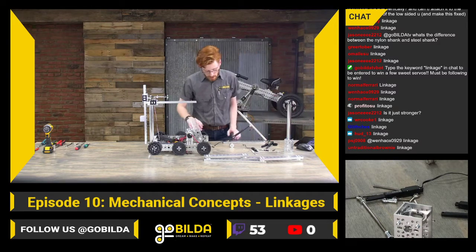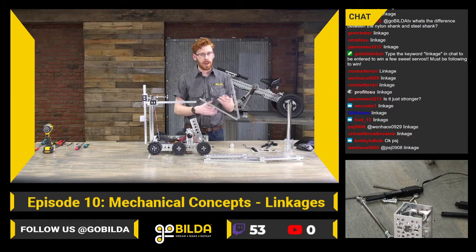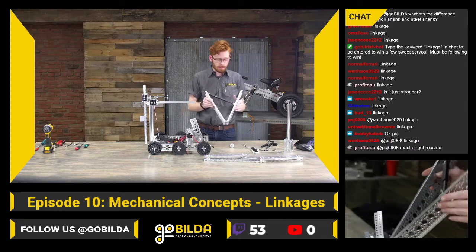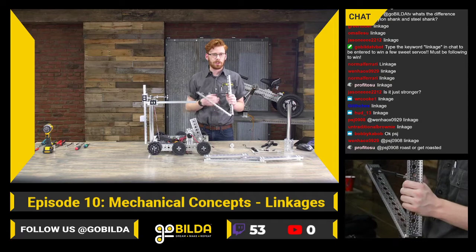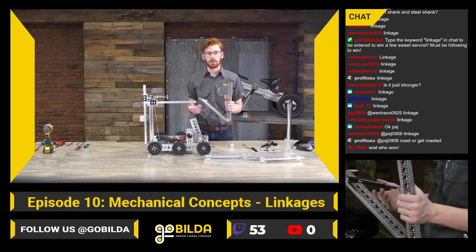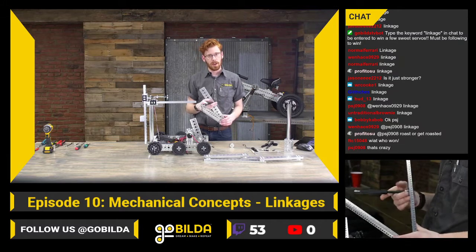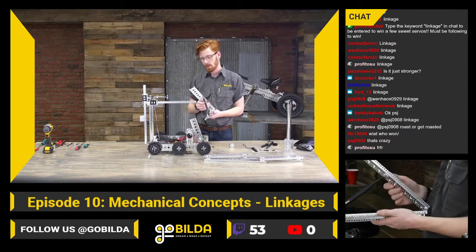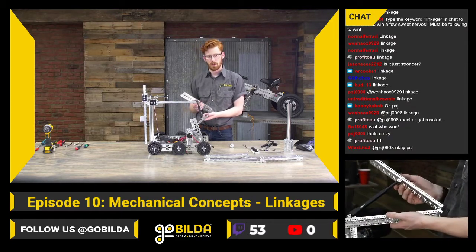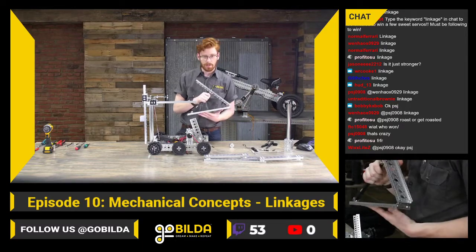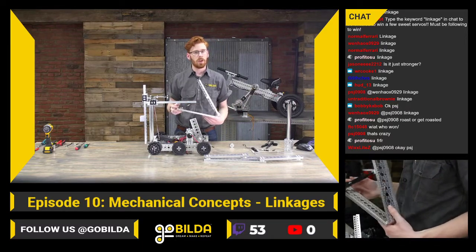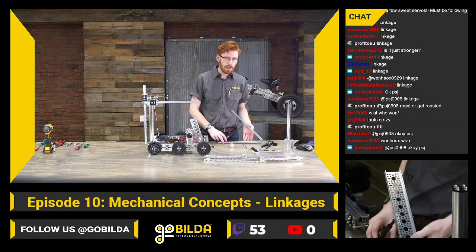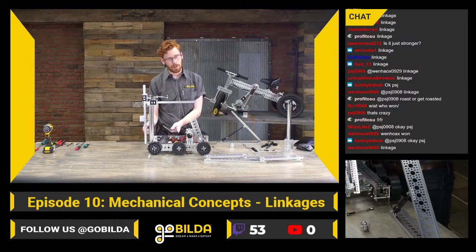So, if we want to, we can look a little bit more at how linear servos and other linear mechanisms tie into linkages. Because most of the time, I don't see customers using linear servos to actually move something linearly. They're actually going to want to move something rotationally and use that linear force to really get a lot of drive on that system. This is a great simple example of something you would use to say lift or tilt a shooter, or open a trapdoor in a mechanism. And it can have really a lot of power depending on your application.